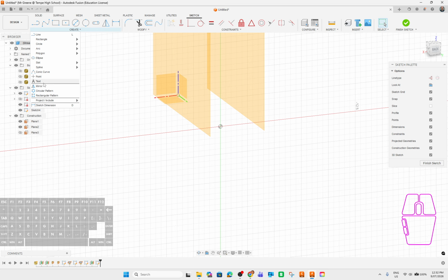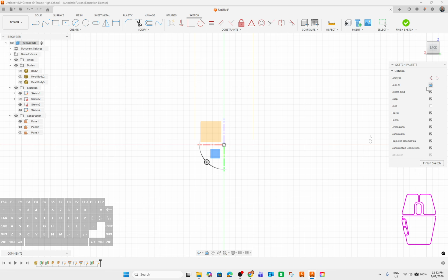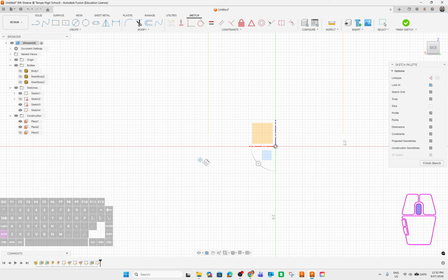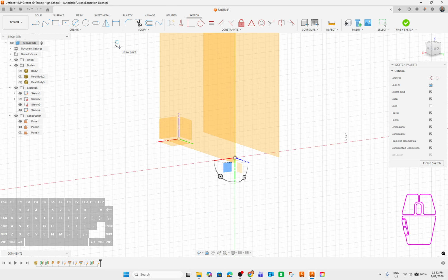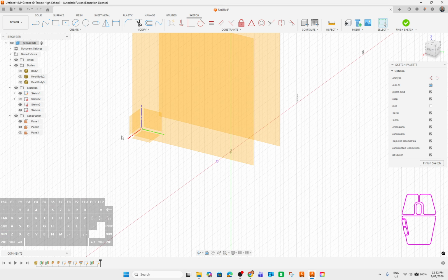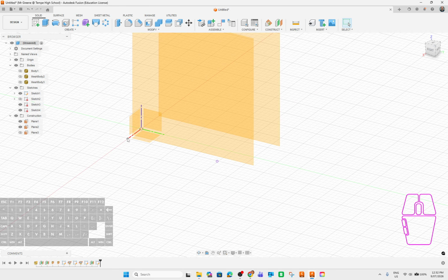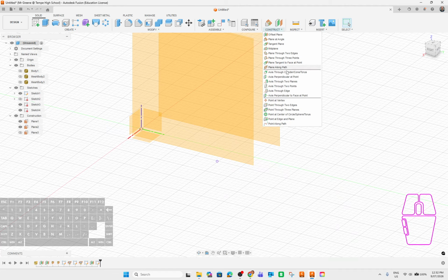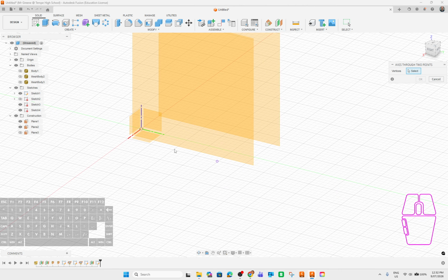So if I go here, create point, and just hope that, or I can even project it if I wanted to. So go here and just feel along that line until I've got it. All right, if I can't find it, I'll use the project button, shortcut P, and just go along that line, and you'll see that'll project that point there for me. Then after I've done that, I'll go finish sketch and construct axis through 2 points, this point, and then I've got my axis.